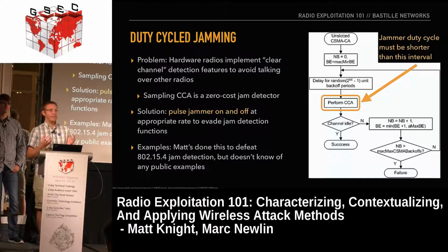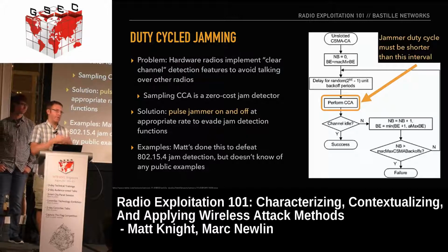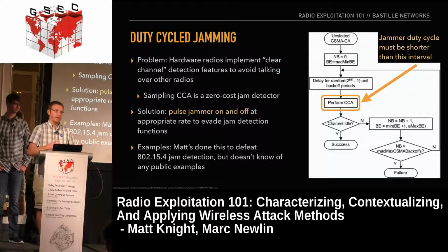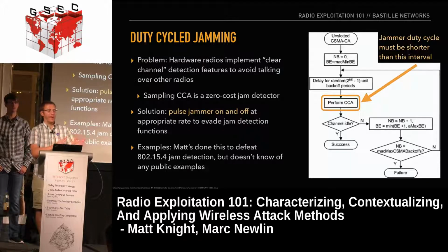This actually gives them enough data to be able to detect a jamming attack. So for example, if we have a protocol that has a 9 millisecond packet length, the normal behavior would be for the channel to be occupied for 9 milliseconds and then go silent. If the channel is occupied for 10 milliseconds, this is longer than the average or normal packet length, then the device can say, okay, somebody's potentially trying to jam the channel and then change its behavior.